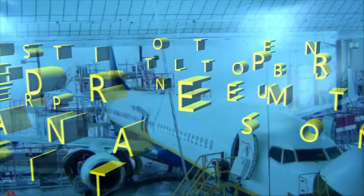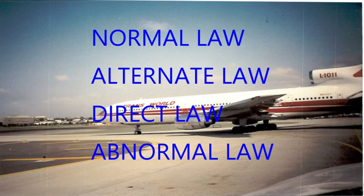So here in this particular case, there's normal, alternate, direct, and abnormal law. And be aware that this is specifically Airbus. When we get to Boeing 777, the terminology may be slightly different regarding the modes of protection in the different phases of flight. Here on Airbus, there are the 4 different ones: normal law, alternate law, direct law, and abnormal law.